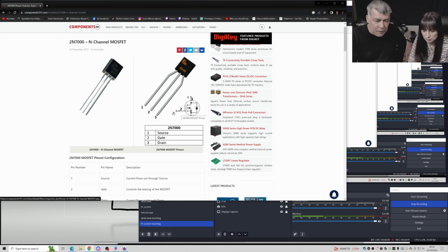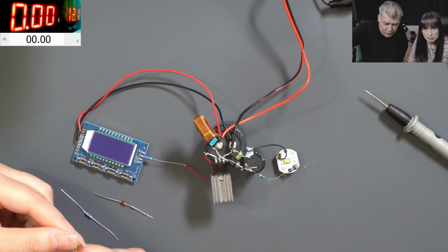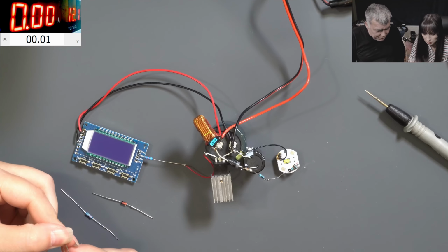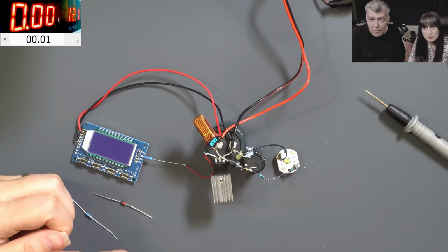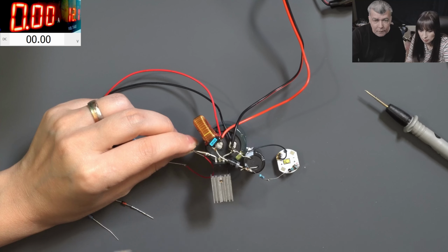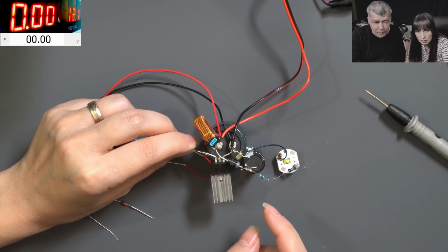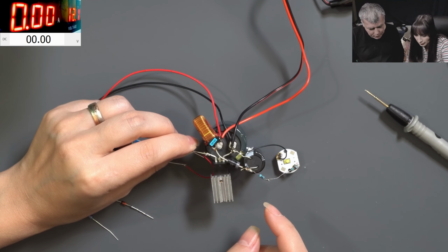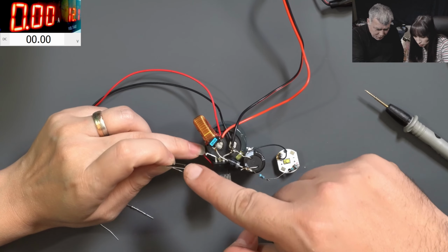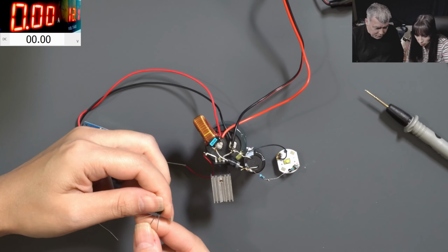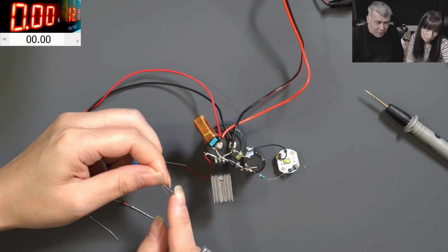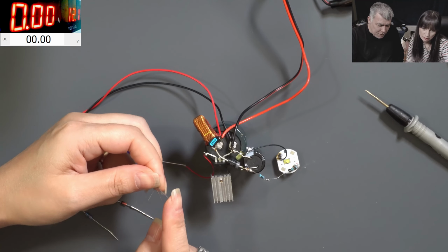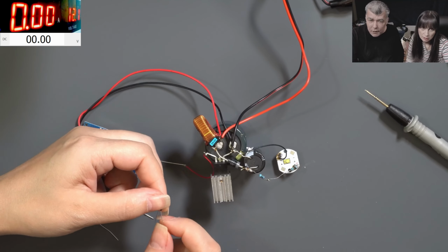Source, drain. So take the solder iron and let's do it. Give me the schematic first to see. Give me 1 second. The gate has to be with the drain. I don't think that's the drain. You sure that's the drain pin? From this MOSFET? No, this is the drain. You see? Yes, this is the drain. So you were about to make a mistake.